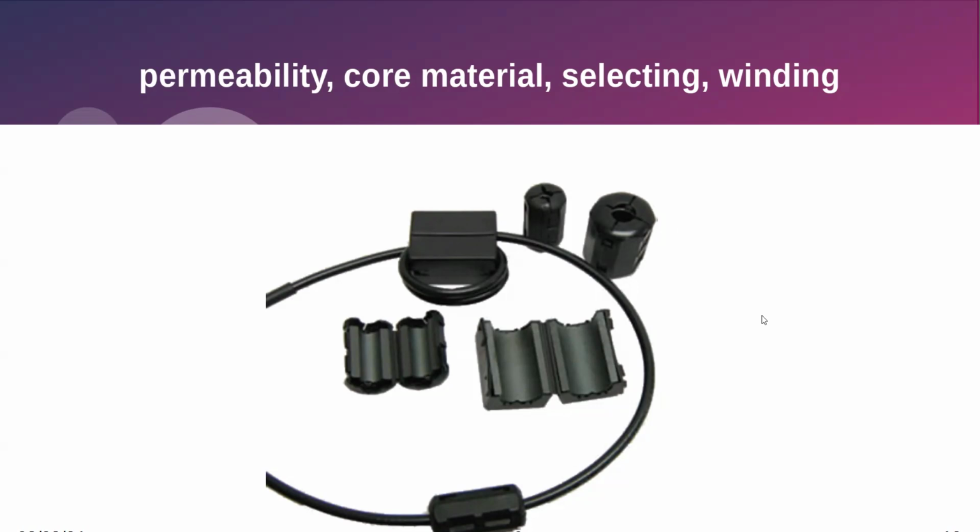Here are pictures of some of the clip-on ferrites, which you can use for EMI suppression. You can also get cables built with them. You've seen them, USB cables and others you can buy with those already installed on them, or you can get these clip-on do-it-yourself. It helps eliminate RFI that may be running around in your shack.